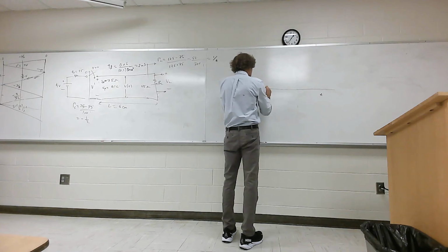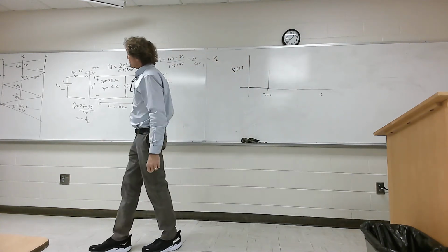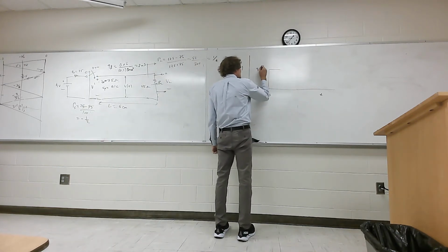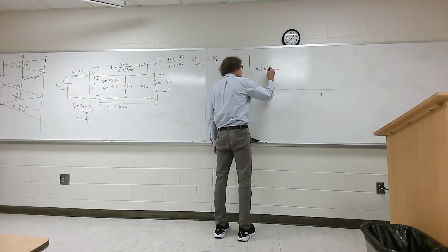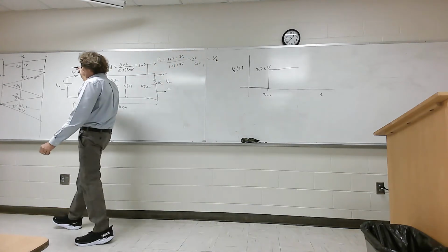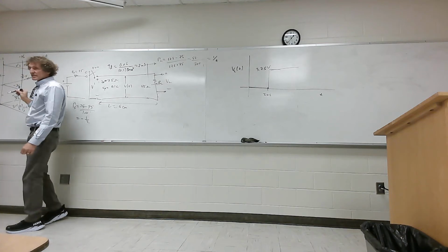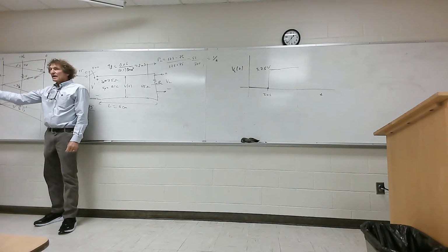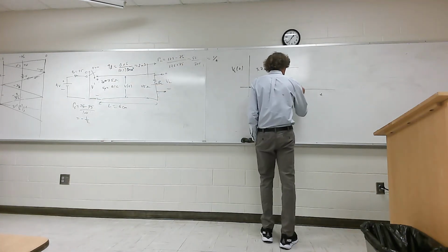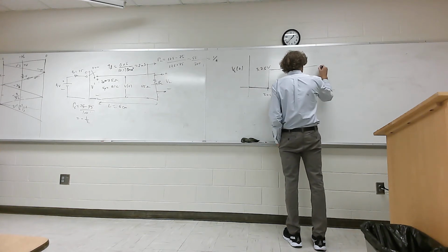And at 2 nanoseconds, it goes up to a value of, what was the sum of these 2? It's 3.75, right? So it goes to 3.75 volts right there, and it's going to stay that way until what? Think about it. That's 6 nanoseconds, correct? Y'all follow? It's the full bounce now. It's got to go back and then back again. So now, that's 2, this would be 4, and this would be 6 nanoseconds, and then at 6 nanoseconds, what happens?